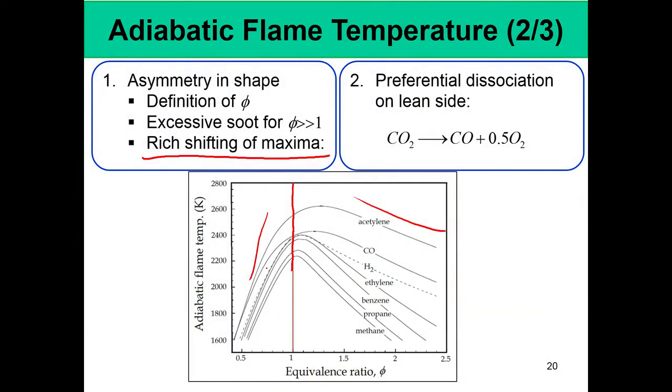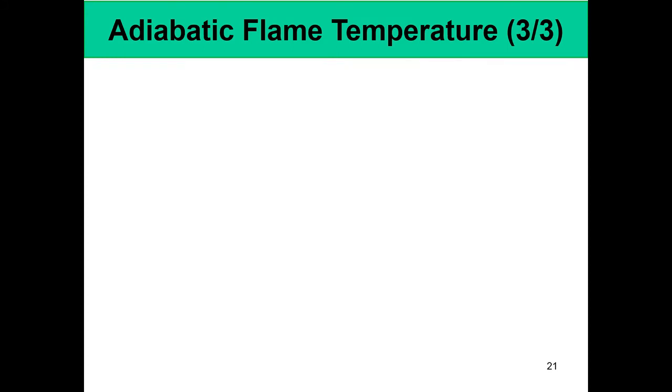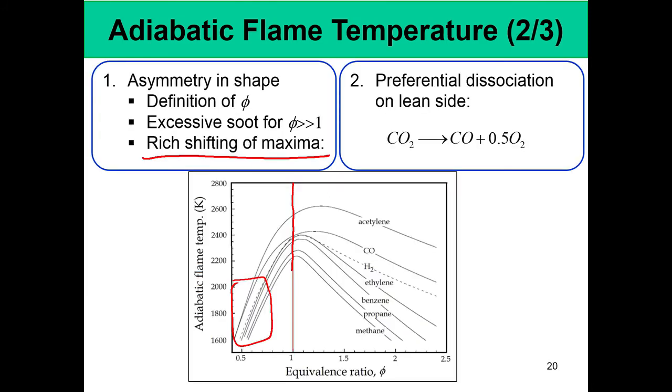Now, this is very important, and this factor needs to be noted if you are designing a standard combustor. Of course, you will see later that the adiabatic flame temperature also determines the pollutants that will be emitted, and presently everybody wants to work in a regime where the temperature can be lower, there is no soot, and no carbon monoxide formation, but there are other challenges associated with this, which we will talk about later. Coming back to dissociation, you will see that with increasing pressure, the adiabatic flame temperature becomes more and more peaked towards stoichiometry.